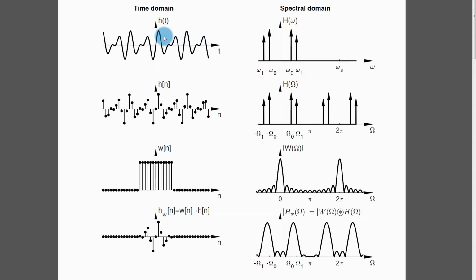In the time domain, it is rather hard to see that this is a mixture of two sines, but in the spectral domain, you can clearly see this. Now, what happens if I measure this signal in real life? I have to sample my signal, so the spectrum becomes periodic. Not a big deal. And I have to record only a finite number of samples.